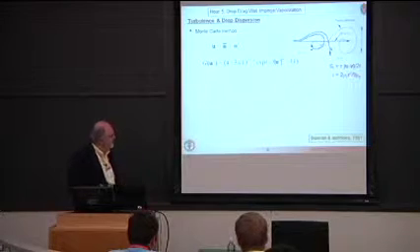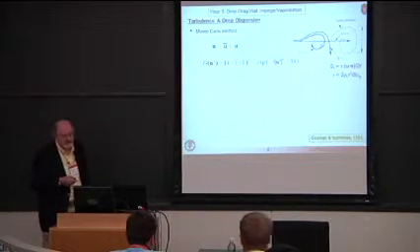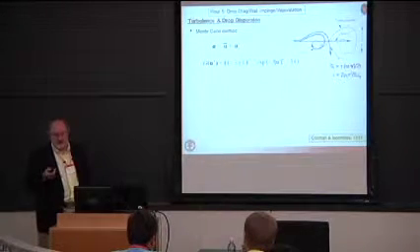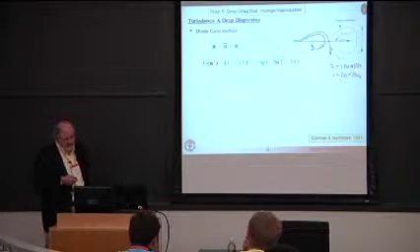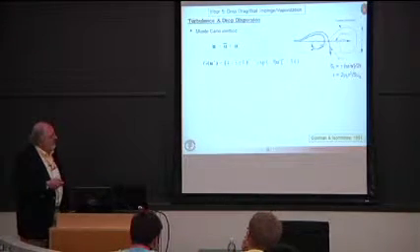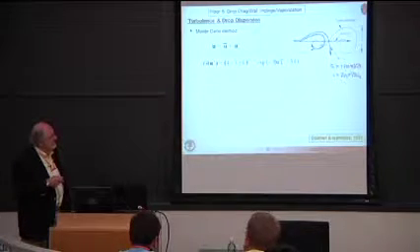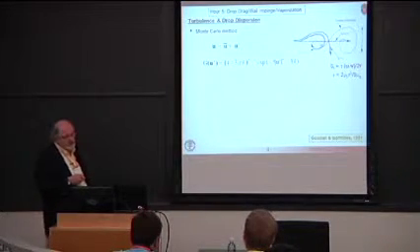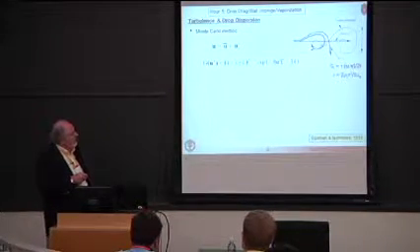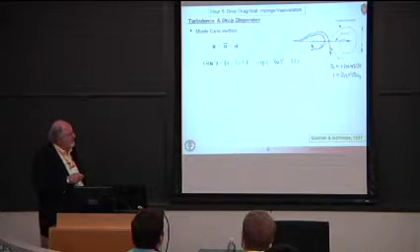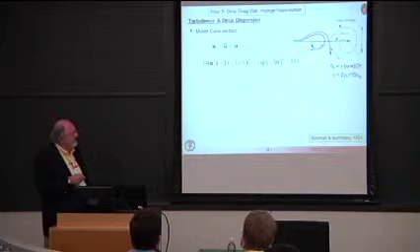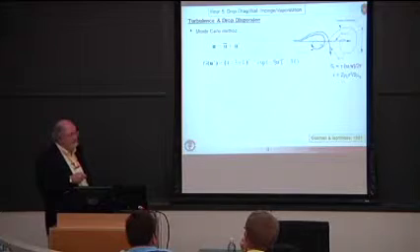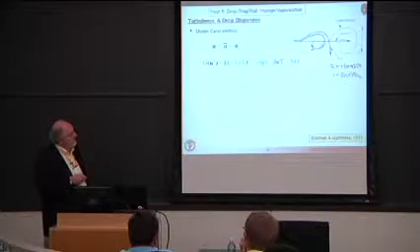Okay, so the other aspect is the relative velocity between the drop and the gas, and this goes to your question earlier: the droplet is going to be influenced by the turbulence in the eddy that the droplet is located in. This picture over here just shows conceptually the types of interactions that you might expect between a droplet and a turbulent eddy. If you imagine vortices in a flow, those vortices have a certain characteristic time, and droplets have a certain characteristic time to adjust to the flow in that vortex. The measure of that is this